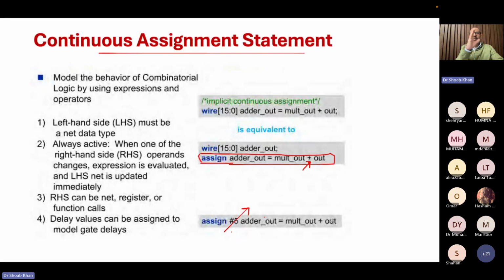Sometimes it is very cumbersome to understand what your Verilog code is doing, because everything happens at zero simulation time. If there are 1 million lines of code, every one gets executed at zero time of simulation, and all values will change. It'll be very hard for you to understand what change has resulted in subsequent changes in your code.